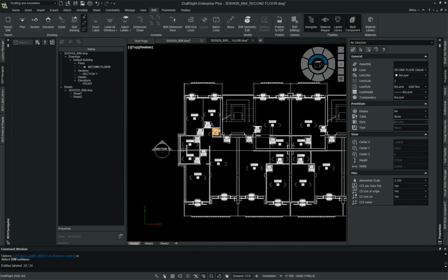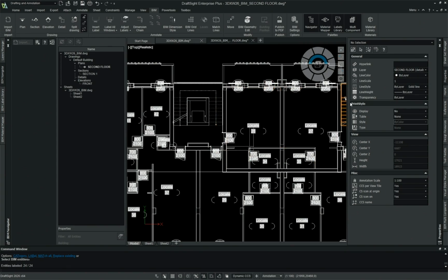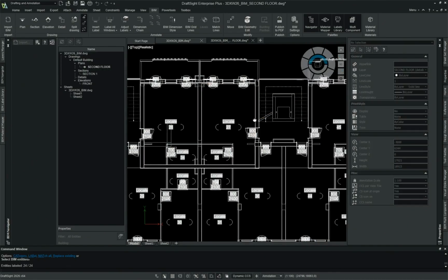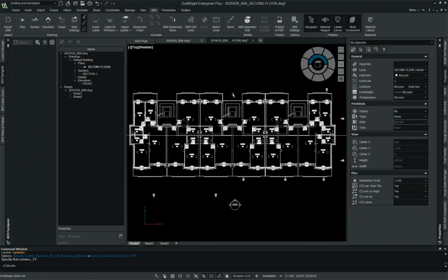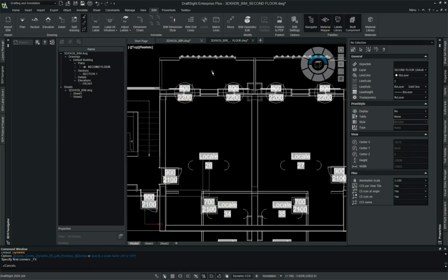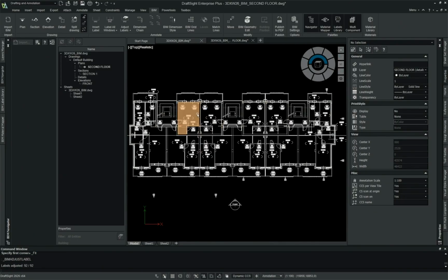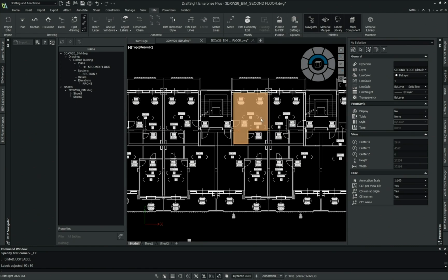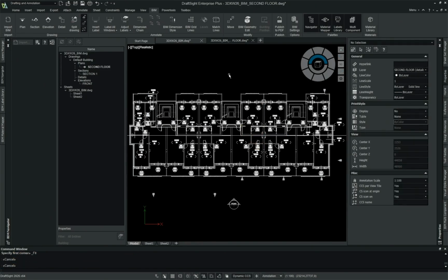So you can see with just a few clicks, we've correctly labeled with some of the geometric properties of the windows, the doors, and the rooms. We've added all of these labels that are consistent with the Revit model. And obviously you look at these window labels, and that text is hard to read because it's right on top of the geometry. So we have the adjust labels command that should shift them all slightly so that they're much easier to read when these actually get printed out. Really nice. So I'm going to go ahead and save this.